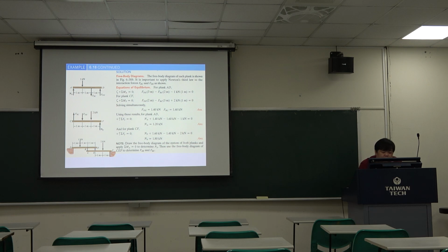of equilibrium. Because we want to get BC and DE, just choose the one and then start your calculation. Okay, you can see so many forces are parallel to the y-axis. So we don't do the summation Fx, because the summation Fx equals 0 and there is no acceleration force.